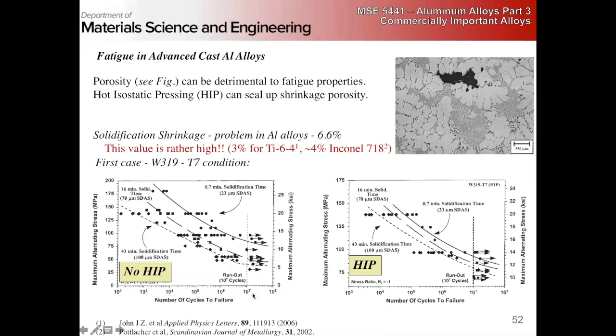So chances are you're not going to start your car 100,000 times over the life of your vehicle. But if we have a high stress state because of shrinkage and microstructure evolution, it might not be out of the realm of possibilities that you might have 10,000 engine starts, rather than 1 million.